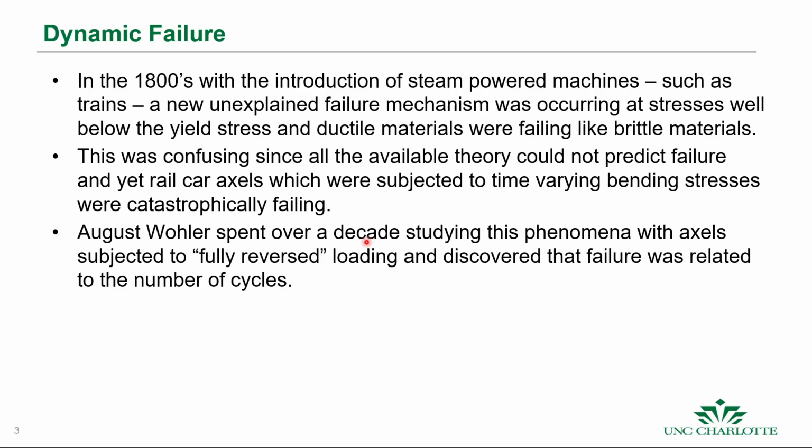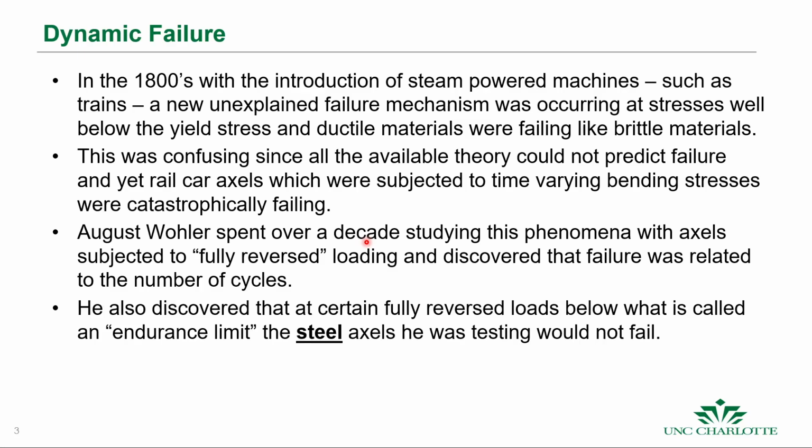And he discovered that failure was related to the number of cycles. In fact, he also discovered that fully reversed loads below a certain threshold resulted in specimens that wouldn't fail in the steel axles he was testing.